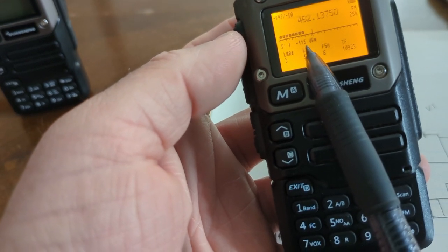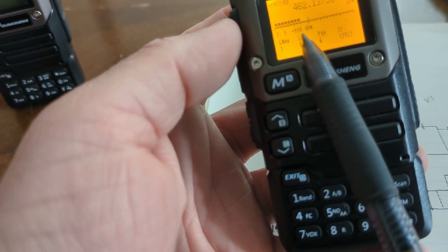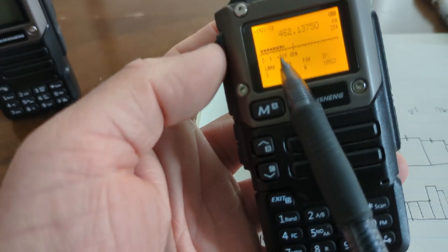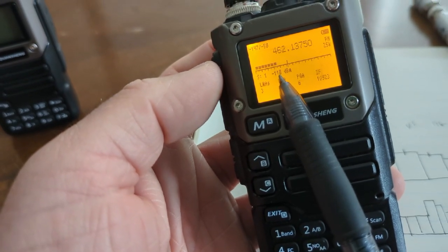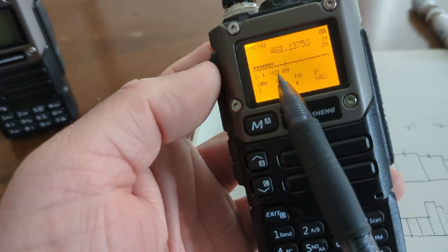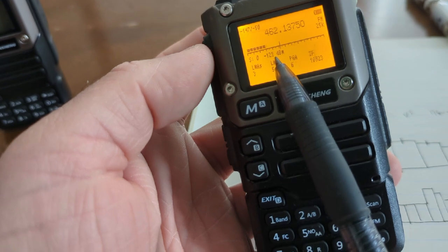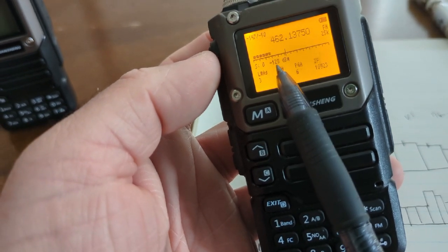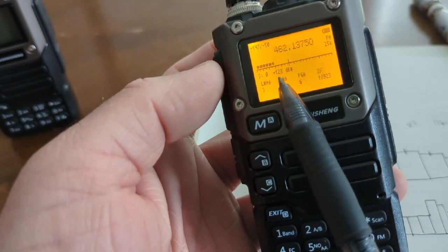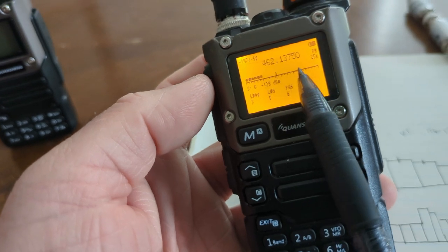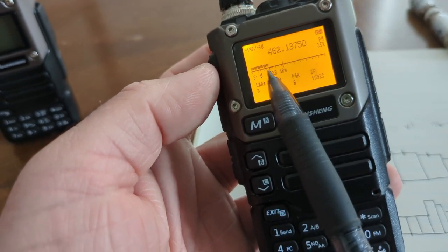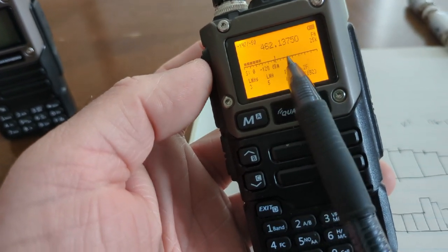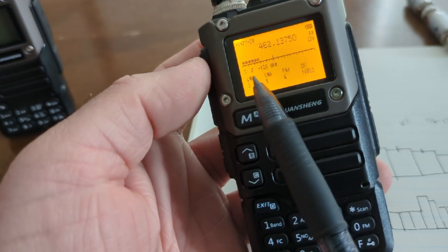It's a negative number, so the stronger the signal, the smaller this negative number gets. So if you write that down at a given point, you can tell if your signal is getting stronger or weaker pretty accurately, right? So the stronger the signal, the further to the right, the smaller these numbers get. The larger these numbers get, the weaker the signal, the further to the left, right?